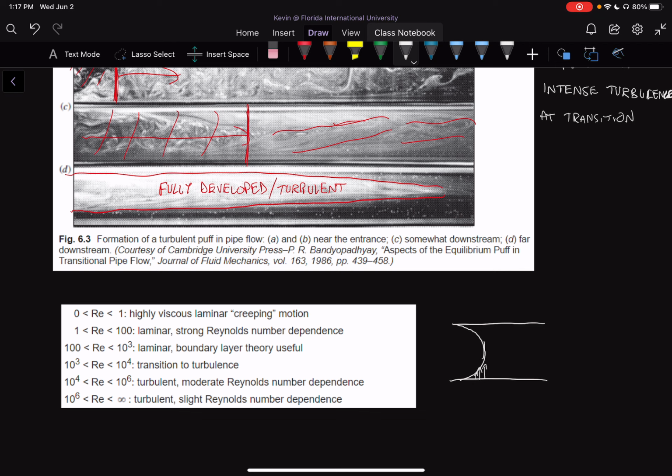The Reynolds number is approximately a value at which transition is known to occur. This critical flow is known to start occurring around 2,300, but it could be occurring at 2,000 or at 1,500 or at 5,000. It's not a precise science. It's again from the randomness of the flow. There's a lot of different things that can happen that create this transition to turbulence.